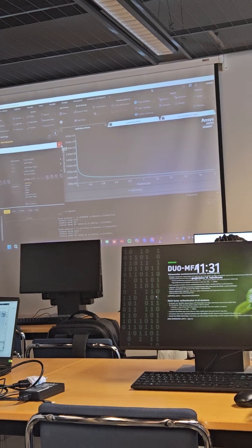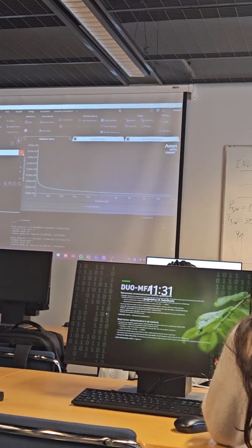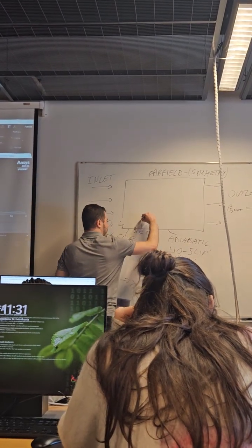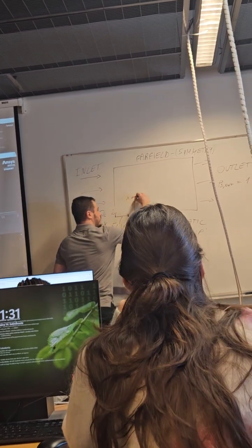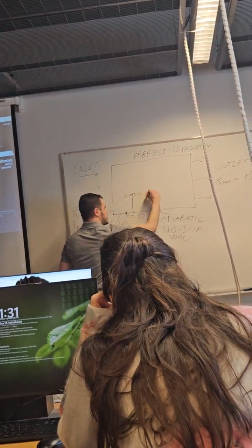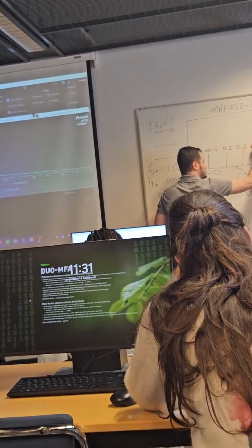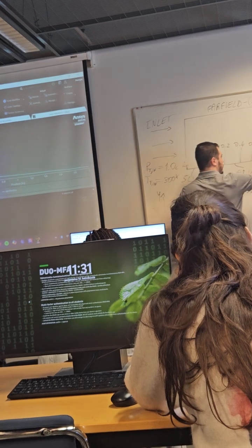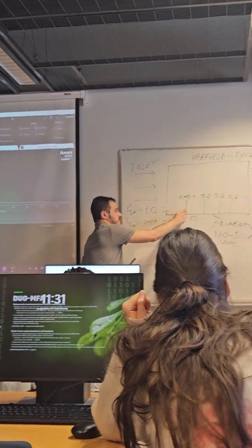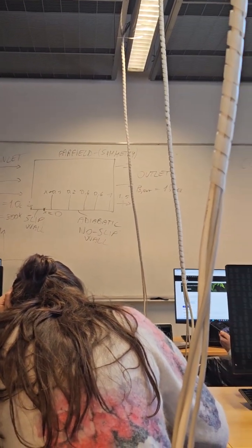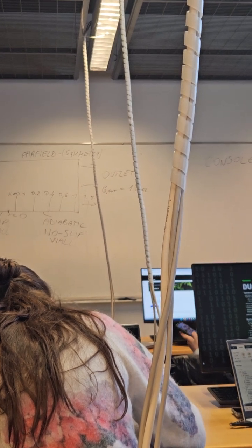So what we will do is create a series of lines in the domain, perpendicular to the plate, at x equal to 0.1. We create another one at 0.2, 0.4, 0.6, and then 1 and 1.5. So we create several lines where we can then plot or extract the flow quantities all over these lines.